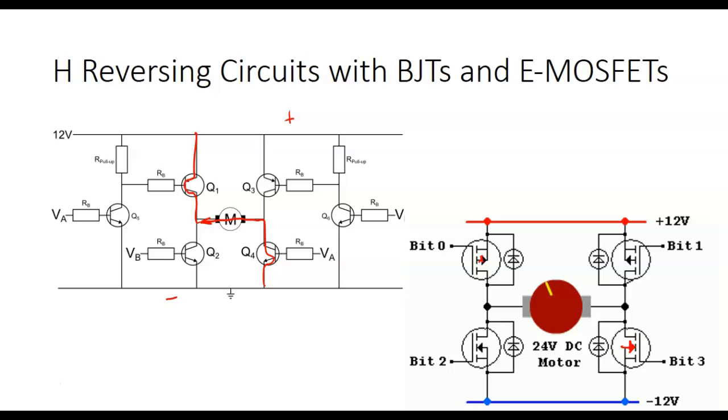Rule of thumb, if you don't have the chart, if you look at most motors now, there's a code on there, and you can look it up on the chart, and it will tell you the multiplier to use to figure out what we call our starting current. Well, the problem is if you reverse this thing and you don't let it come to a stop, it's going to pull that full load current until it changes directions. So it's pulling the full load current a lot, and it could kick your overload.